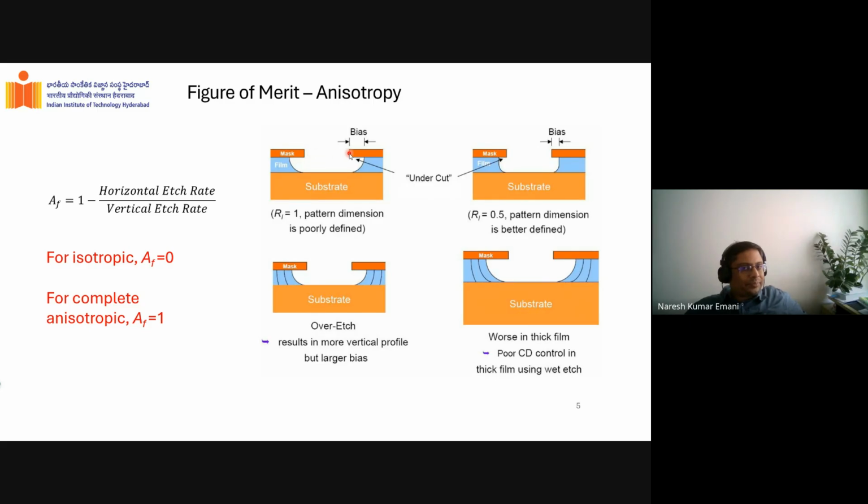The question is, we understand that you have an isotropic process, there's a mask, there's going to be an undercut like this. Why can I not simply, let's say this distance was X, make it smaller, some X minus Y, so that I can take care of the undercut also? Can I not simply do that instead of developing this complex etch process? What happens if I do that?